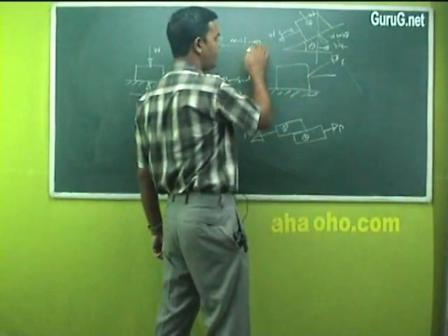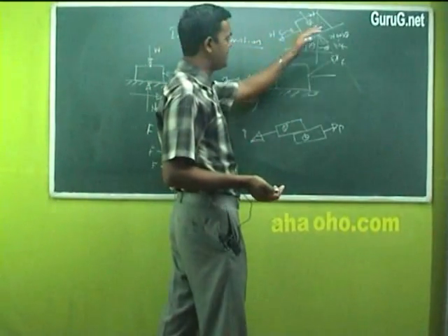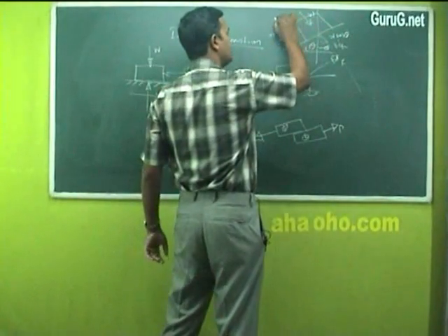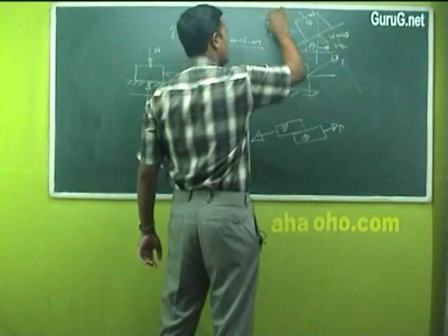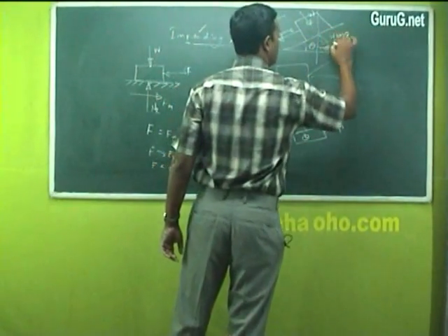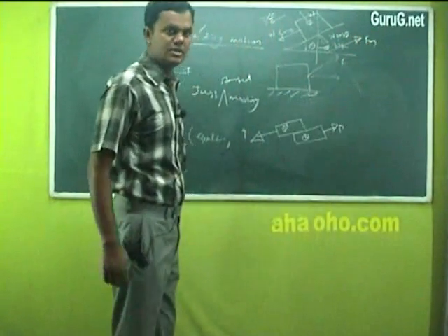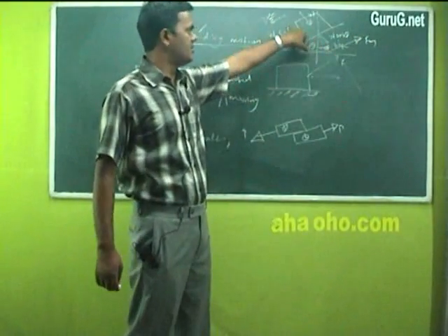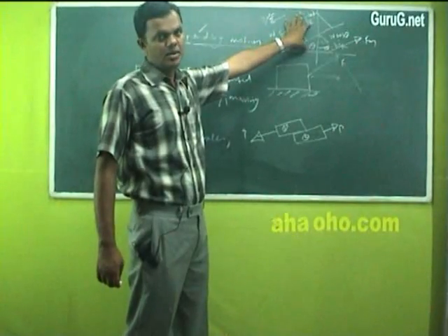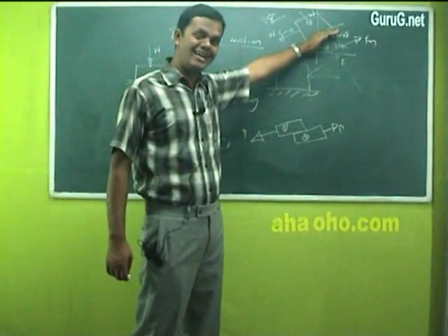So if this is an inclined plane also, what is the meaning? Suppose this body is moving in this direction, this is the direction of motion, what will be the friction here? In the same fashion, friction will be in the opposite direction. So if your Fm is equal to that particular value of W sin theta, what will happen? It will be in equilibrium. If sin theta component is more, the body starts slowly sliding down.